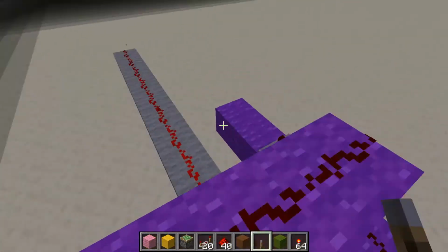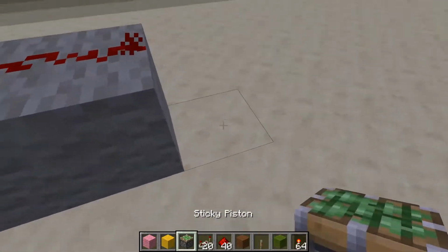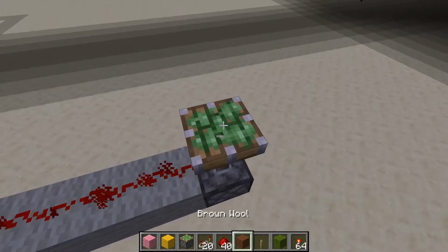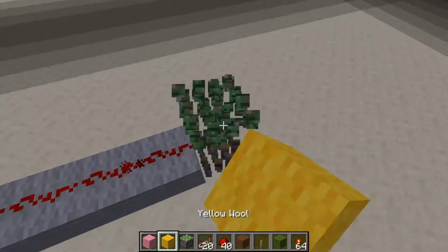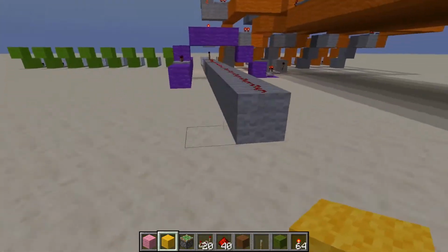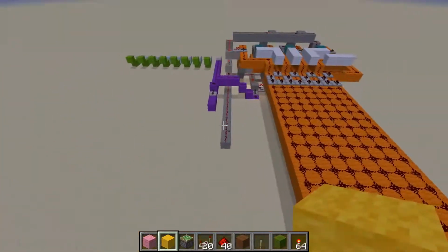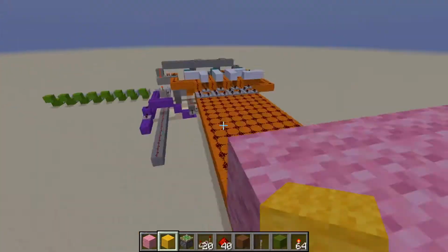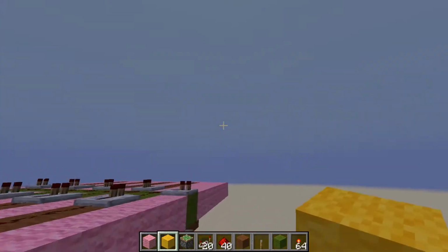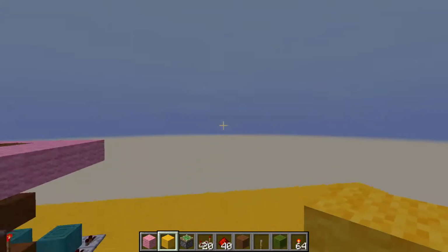Like idiot safe. That's actually the reason why we will implement a pulse shortener here. So we will only get a single starting pulse and therefore not clock our system, because if this stays high for too long, it won't turn anymore.